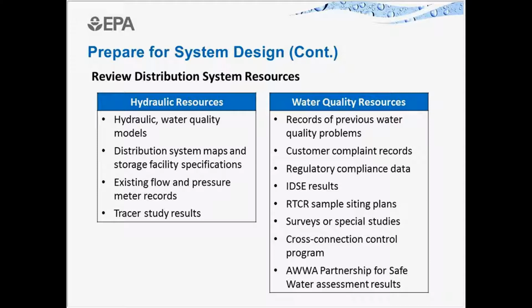You could also use these resources to learn more about potential monitoring locations to inform the design of monitoring stations. And you can also use, say, historical water quality data from the system to develop a protocol for data analysis to help determine for a given monitoring location, what water quality conditions are actually anomalous and which conditions actually occur from time to time at that particular location.